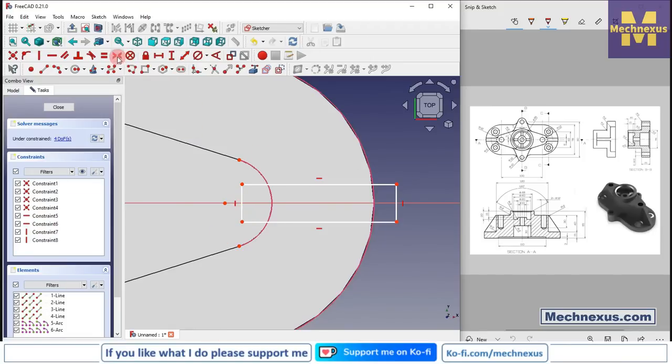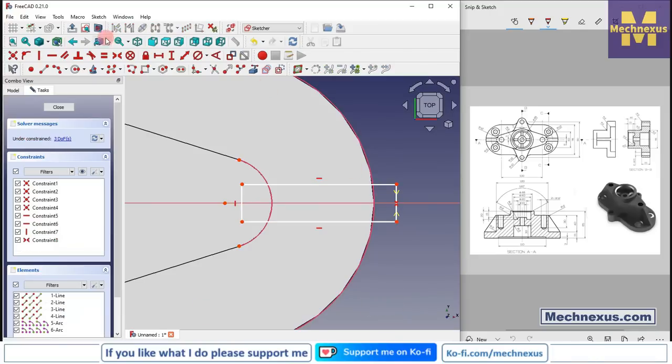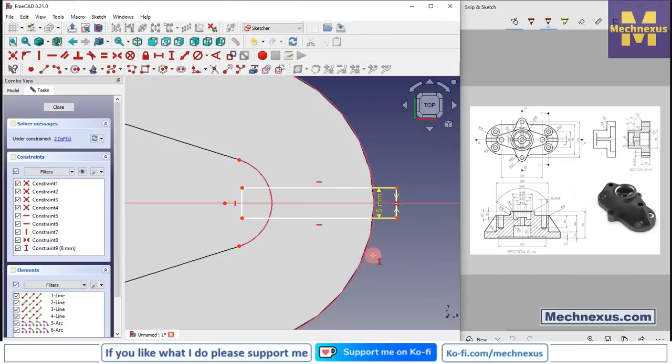So we will use the symmetry, select this point and this axis, and we will delete this over conflict constraint, select a vertical dimension and provide 8 mm,